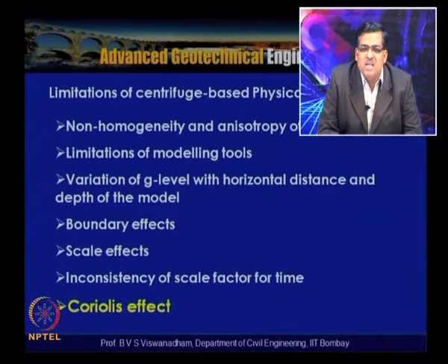So this inconsistency of the scale factors for time is also said to be one of the limitations. Sometimes when the scale factors for time for dynamic cases and for diffusion cases are different, and the phenomena occur simultaneously, then we have to resort to some sort of alternative so that the scaling considerations are satisfied.